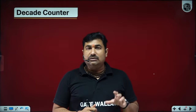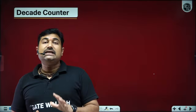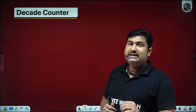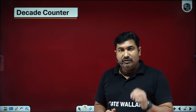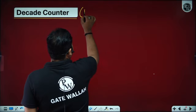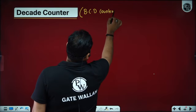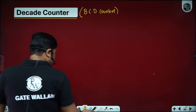But if the decade counter counts in a sequence from 0 to 9, it is called a BCD counter. So always remember, all BCD counters are decade counters, but the reverse is not true, because a BCD counter will have 10 different states, but in a sequence of 0 to 9 binary. However, a decade counter will have 10 different states in any sequence. All BCD counters are decade counters. Is it okay? Yes, sir.